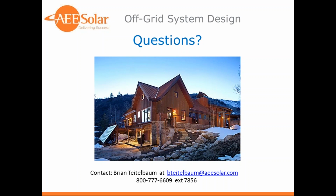Then you need to use the maximum power point voltage, the VMP, in calculating the actual system running, and that's for your wire sizing. So if your array is 150 feet away and you're sizing your voltage drop on your lines, you're going to use your VMP at that point. Three modules in series, for instance, should be running at about 90 volts. In hot weather, it might be 80 volts. So you need to keep that in mind when you're doing your wiring calculations. But it's the open circuit voltage that we're concerned about with the 150 volt limit.